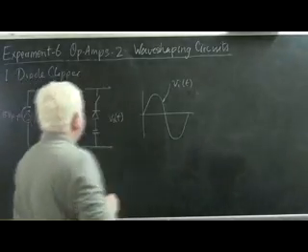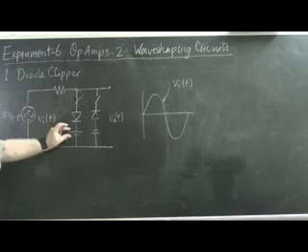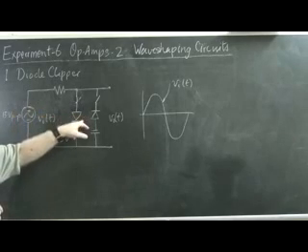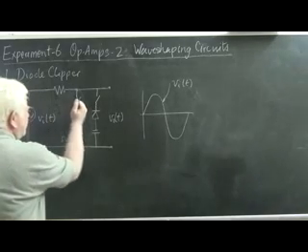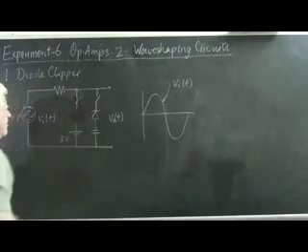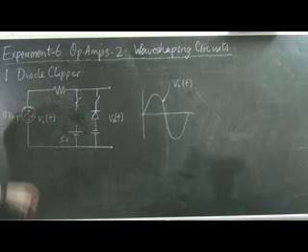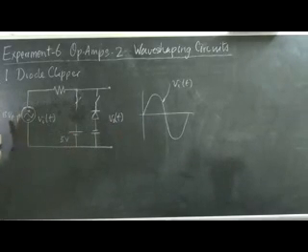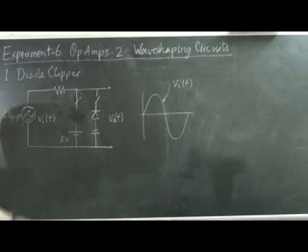As long as the voltage that's appearing here is lower than the battery voltage, let's say 2 volts or 3 volts, 4 volts, this diode will remain an open circuit. So the equivalent model of this circuit will be what you would see if you didn't have this diode, just this. So whatever input signal voltage is applied merely appears at the output with a voltage drop on this resistor only if this output is loaded. Otherwise, it is a 1:1 relationship between the VO of t and the VI of t.